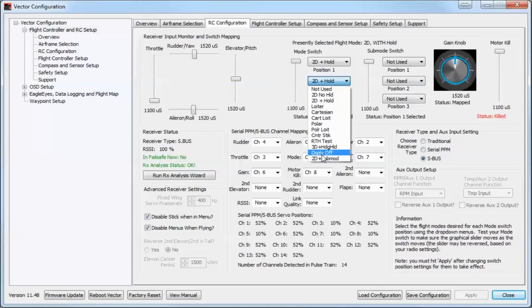The important thing is also that if you have set some alarms in the OSD, there is a function in the OSD setup which is defaulted to being on, which basically says if an alarm warning comes, even if you're in display off mode, bring the OSD back. Obviously, if you look at that and then you want to get rid of it, you can turn it back off again, but the idea is that you can actually get those warnings.